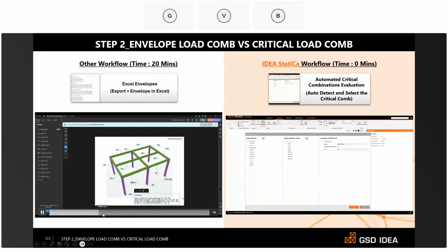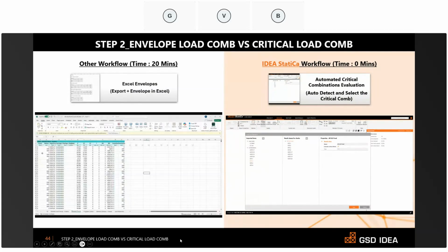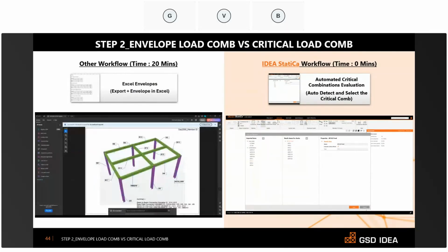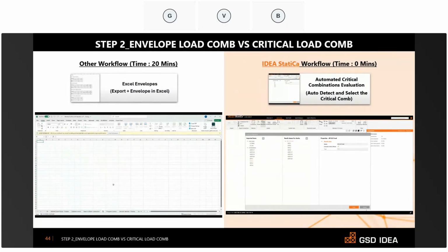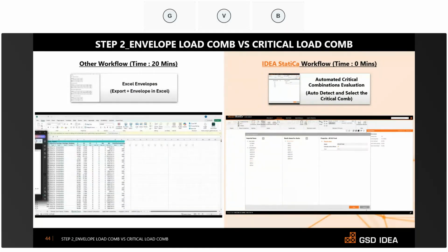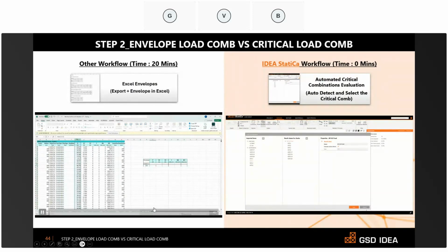Then we have summarized for beam to beam connection. We need only M14 and M15. And finally, we have extracted the membrane forces from the SAP model, and we have started filtering based on those particular SAP IDs, and we started enveloping the cases, like the maximum, minimum, and summarizing it. Like if it's 25.6 or something, then we will approximate to 26 kilonewton, just rounding it off. And similarly, we have done for the rest of the connections, filtering the SAP ID, getting the envelopes,